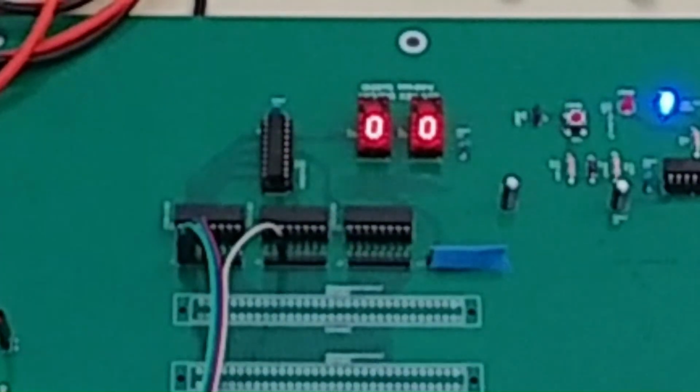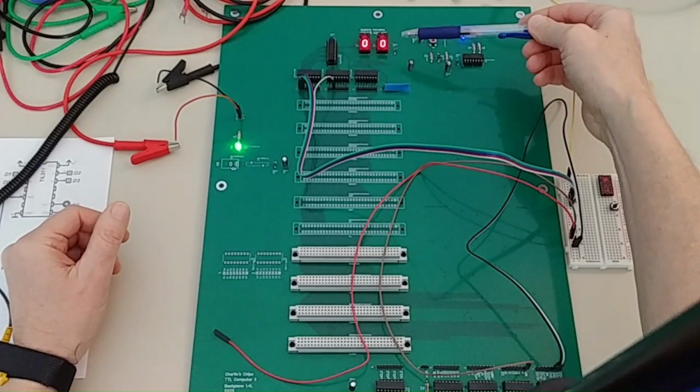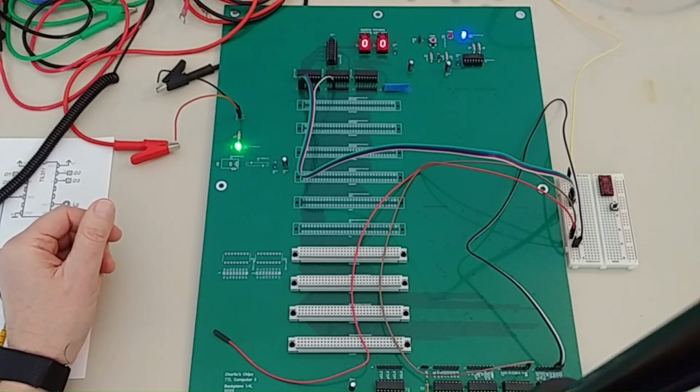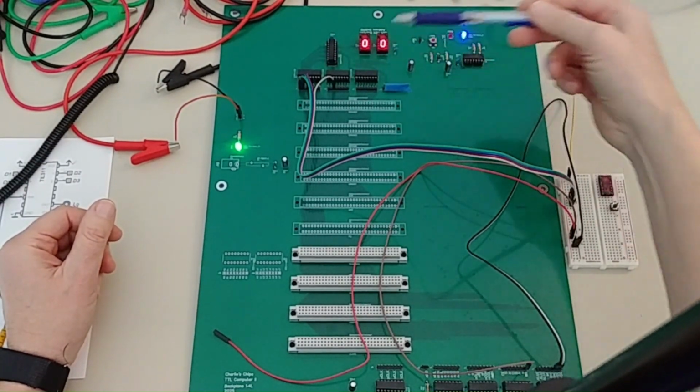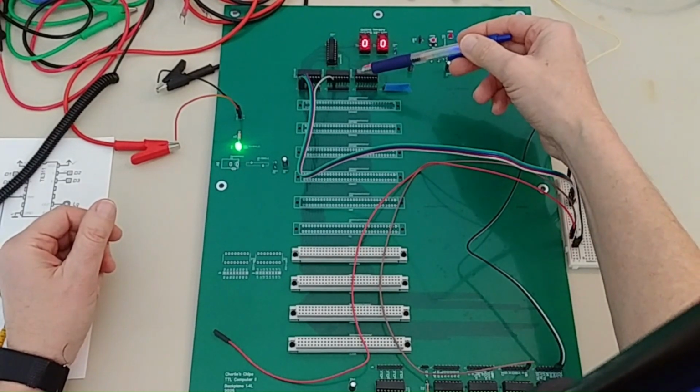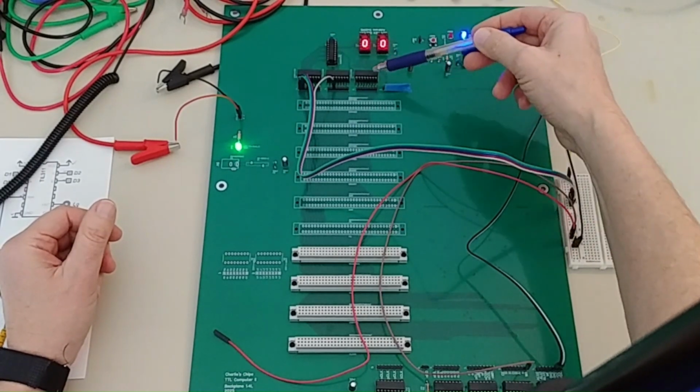All right, so our board is powered up. So we see our hex display is at 0, 0. I said our write signal is already asserted. And what we're going to do is assert the U clock, bring the U clock high, which is the update signal, right? So we already have the address lines patched to 2010. And our data lines are floating high.